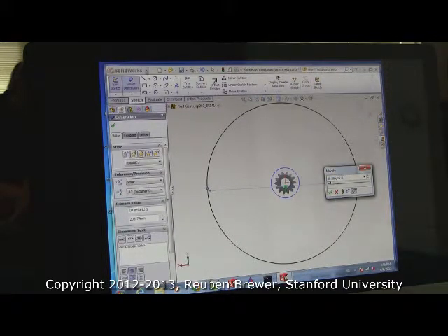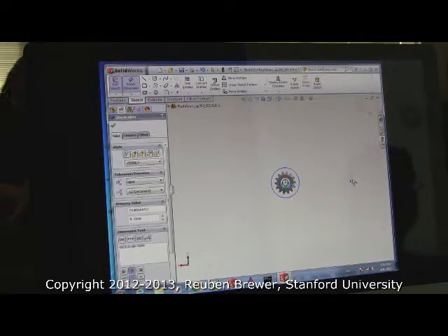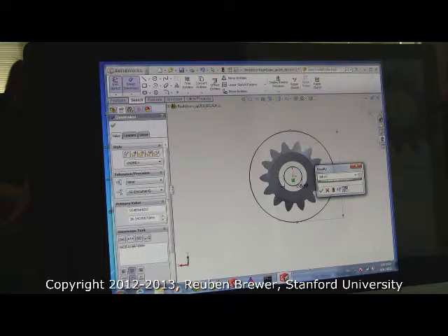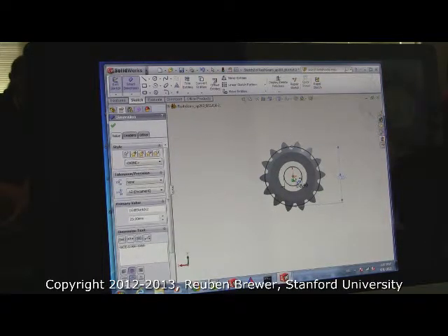And before you hit enter, notice I'm typing an equation in here. It doesn't just accept numbers, it accepts equations too. I could even do this. I could do 4 times 2 plus 0.1 divided by 25.4 and hit enter, and it sizes properly. I actually just typed in 8.1 mm and it worked. Did it really? Yeah. Well, that's awesome. Let me try that. 25 mm. Holy crap! Thank you. That's cool. Okay, so just type in mm.